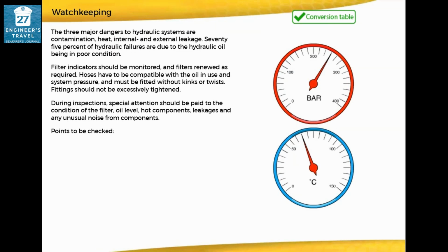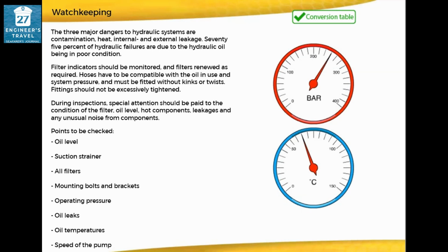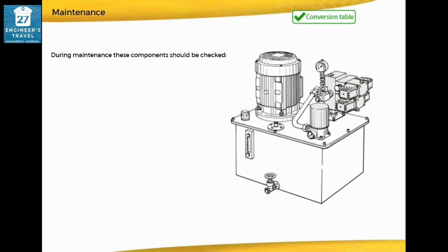Points to be checked: oil level, suction strainer, all filters. Mounting bolts and brackets. Operating pressure. Oil leaks. Oil temperatures. Speed of the pump. During maintenance, these components should be checked.